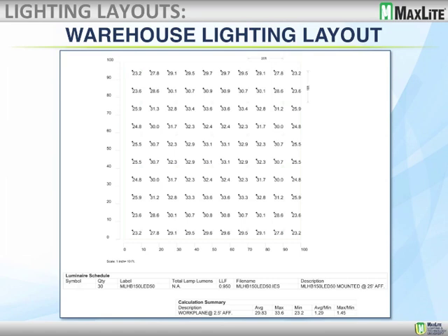So if you go through your IES handbook or look it up, light assembly is approximately 30 foot-candle average. So what we did is we put in our fixtures spaced out, and we ended up at 29.83 foot-candle average. You know, that's a little fudge factor. You're not going to notice 0.2 of a foot-candle difference from 29.8 to 30 foot-candles.